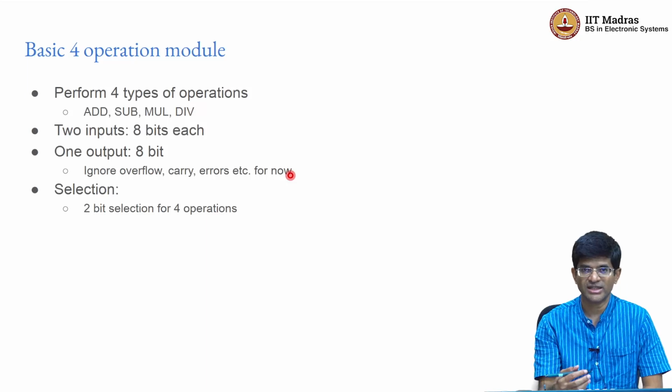If you are actually trying to do, let's say, 32 cross 32 multiplication, right, or a division that requires some kind of fixed point representation of the result, it may turn out that even doing these kind of things in a combinational circuit, or in fact even just doing division in a combinational circuit, may not be very straightforward, right? So right now we are just brushing all that aside, right, saying that okay, these are problems that can be solved. The fact is, even if you need a more complicated circuit which involves, let's say, a finite state machine in order to do the data path and control in order to actually do the computation, that can ultimately be brought within the same sort of purview of what we are trying to do here, right? So okay, so far so good.